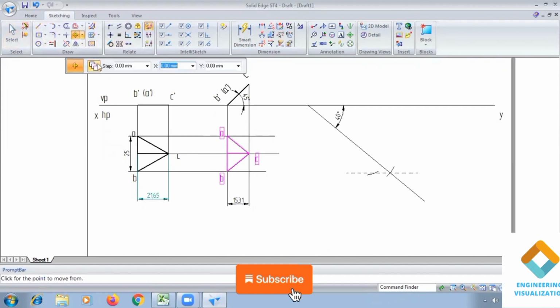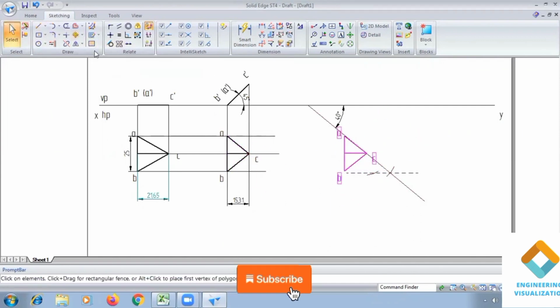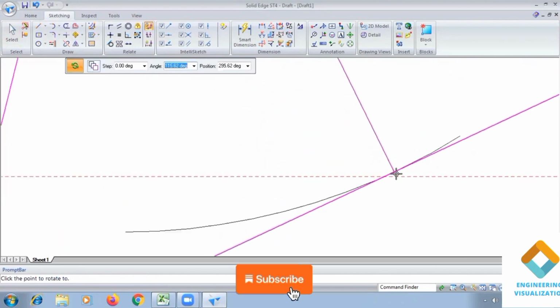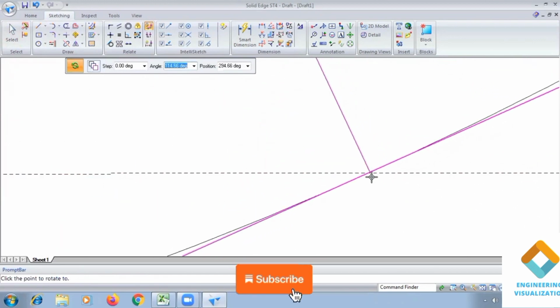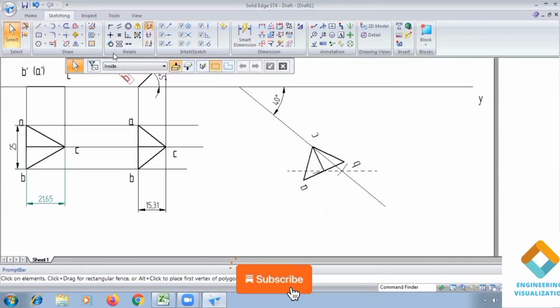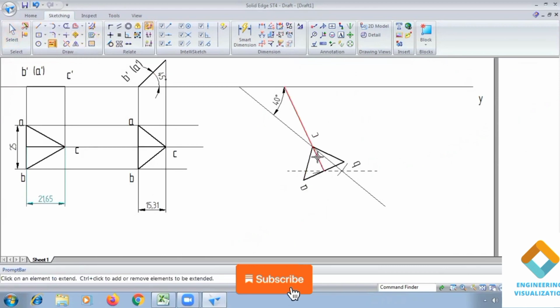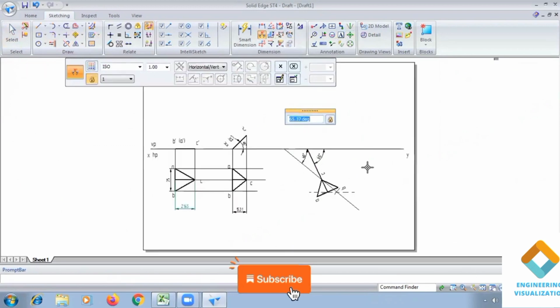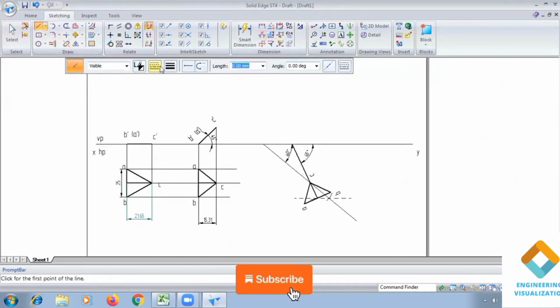So just take this move command, take this reference point, so place it on this reference point. Go to rotate command and take this length and rotate and place it exactly here. Yes, zoom in and place it. Okay, now extend this angle line so that you will get beta angle. So this is the procedure, guys, to do the beta angle. So now project it upward to complete the final position.